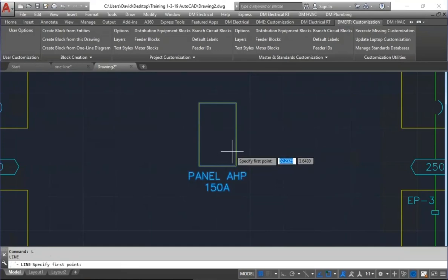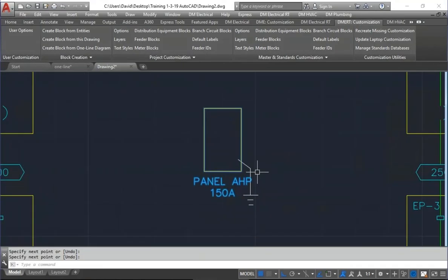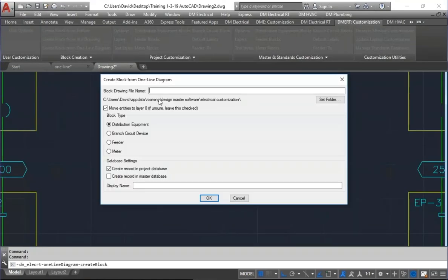Say we have a little ground that's being shown. And this is not terribly well drawn, but you get the idea. So say you want to include that little ground piece and have it included. This will insert that piece as part of the block every time it's used. So I'll add that just as a little additional piece. Create the block.